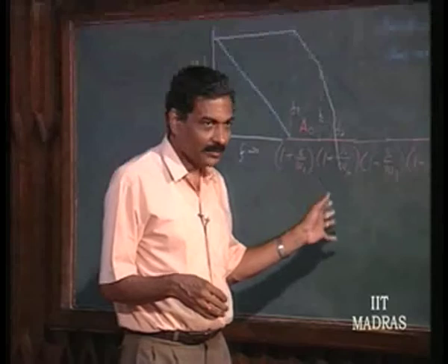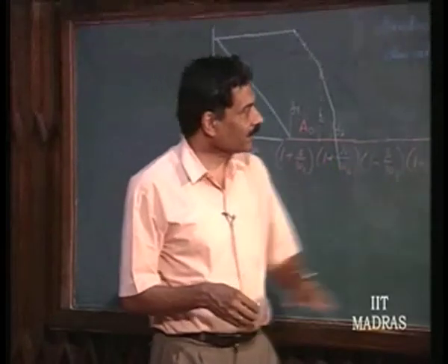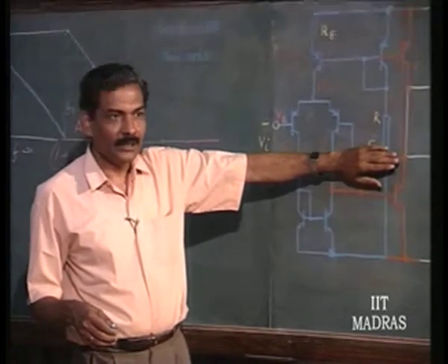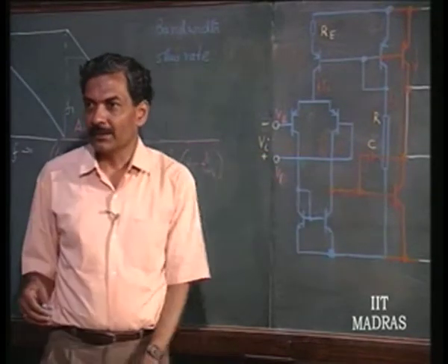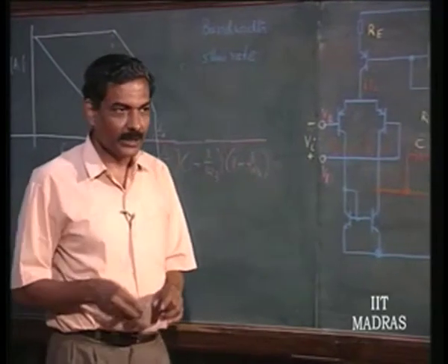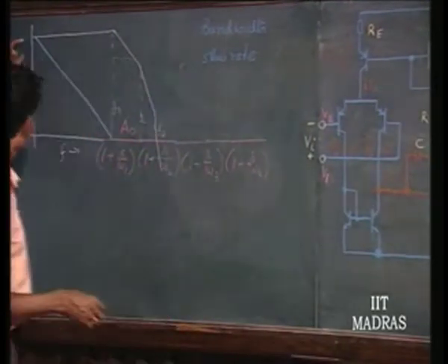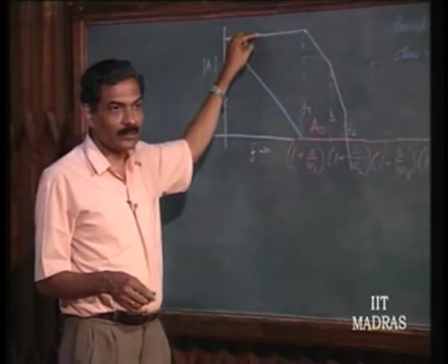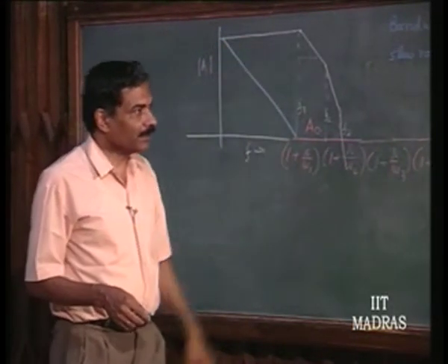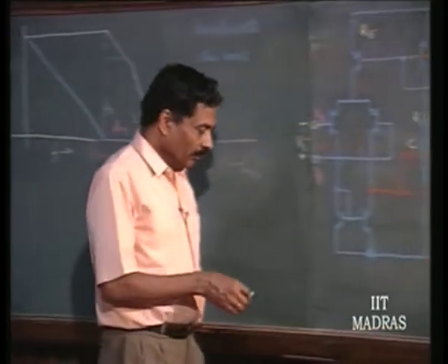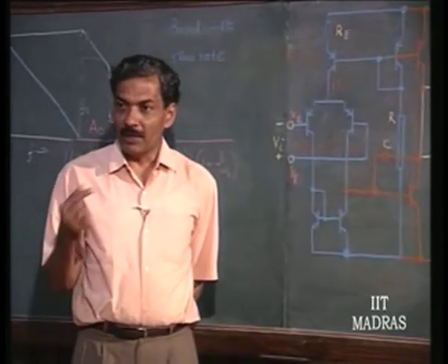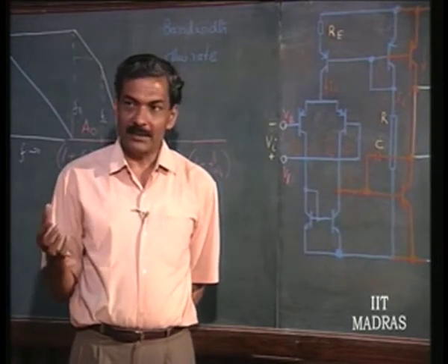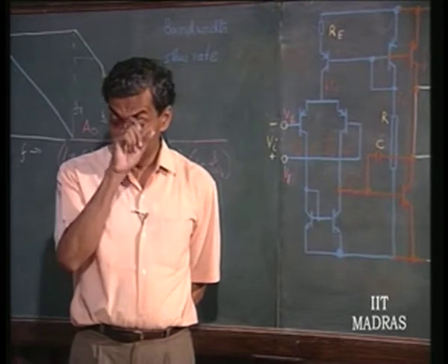Okay. That is why the manufacturers also have given the same configuration almost without the internal capacitor being connected, with a provision for you to connect it, so as to increase the frequency of usage of that. Okay. But however, in this case, they would like to put as small a capacitor as possible inside for compensation, because we know the capacitor takes a lot of area within the IC chip.